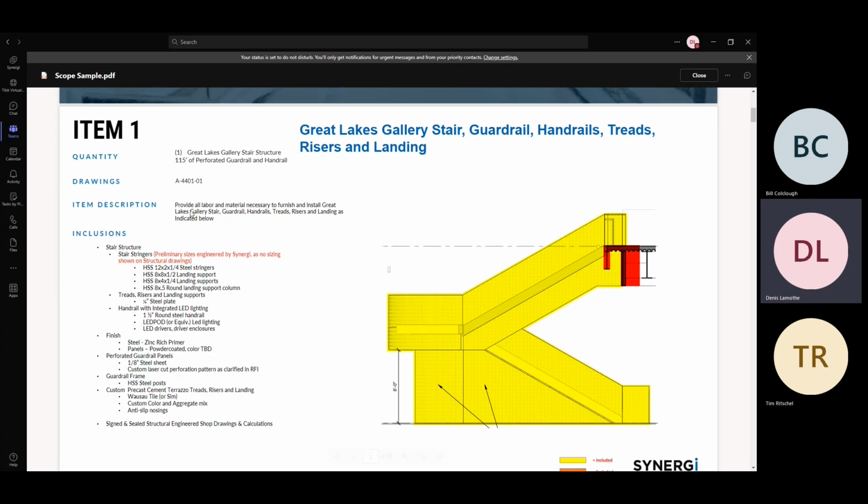So if you don't have a detailed scope of work, or if you don't have meeting minutes from the design assist, then arrange a quick meeting with your project manager and just ask a question like, what kind of finishes are we using? What kind of glass panels are we using? What profile should I have? Typically that's sketched out by the engineer, so you already know what profile to use for your stringers and plates. But if there's any question about that, get together with your project manager. They'll explain it all to you, or should be able to, anyways.